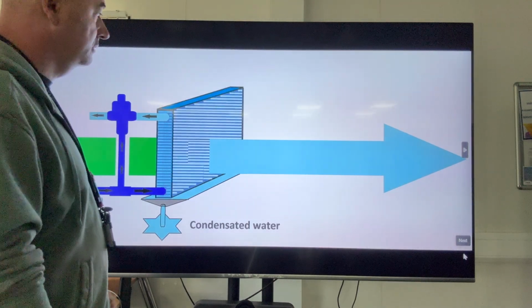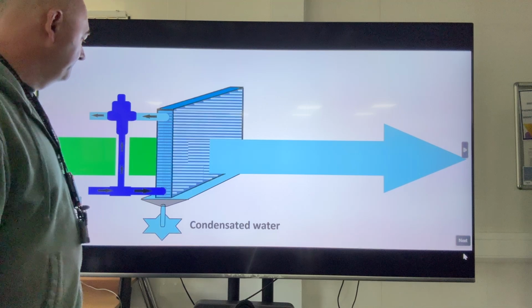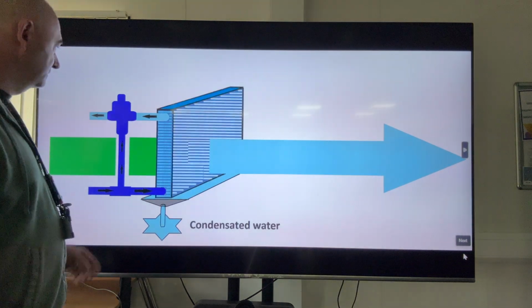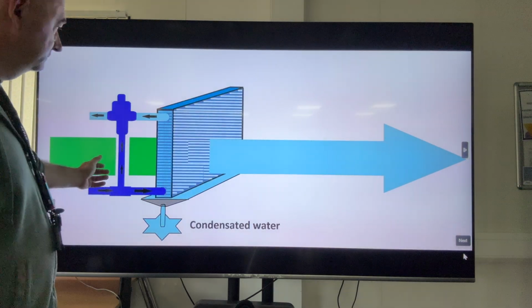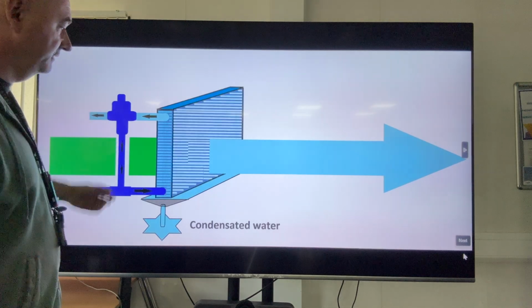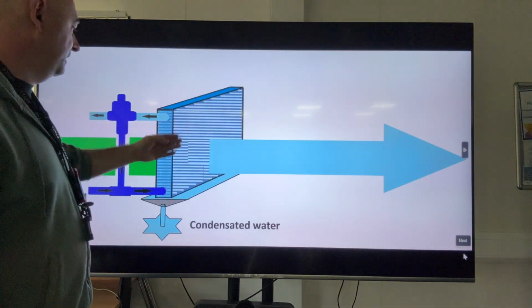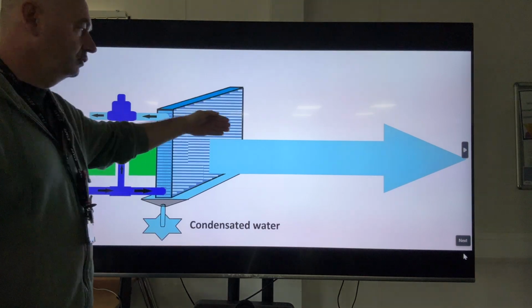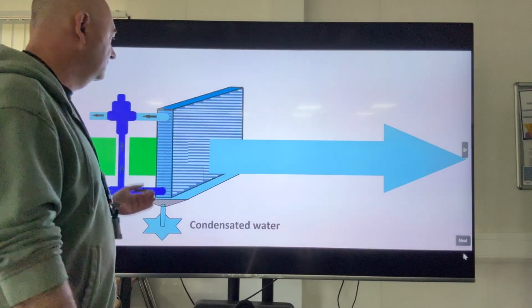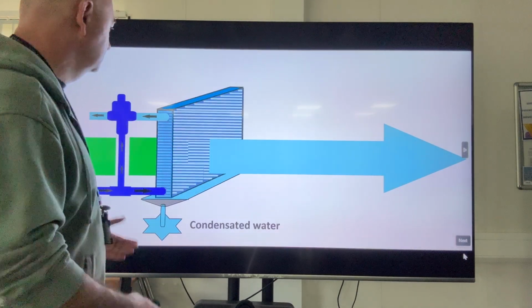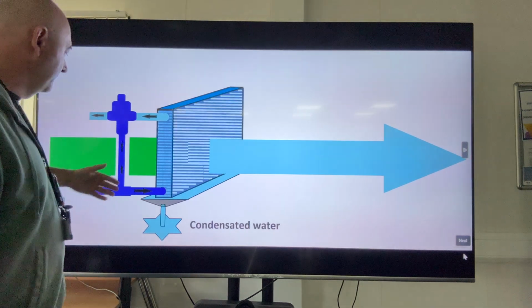I also explain that when people call me stating that the AHU is wrong because the room is too hot, I always have to consider the glycol temperature, the glycol delta T, to see if I have enough flow into the glycol, because these heat exchangers depend on the glycol temperature to cool the air. It's not only the AHU, it is the glycol.